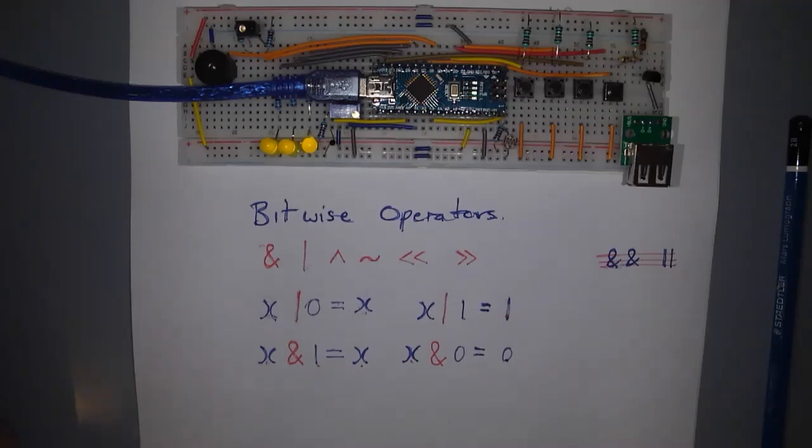The first thing we do is create a temporary variable, copy port B into the temporary variable, and then AND it with this amount, which forces these 3 bits to 0, and then write that to port B. So this single line of operation, line 173, creates a temporary variable, changes its value, and writes it back into the port.